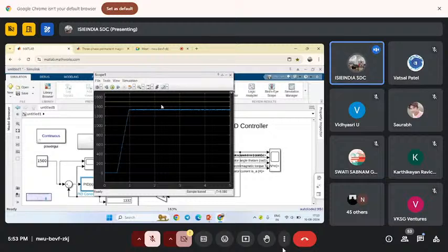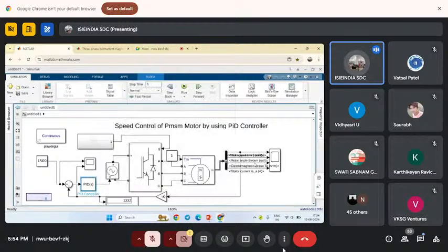It was stuck at 1332 because the KI value should also be taken into account. If you are increasing the KI and KP values approximately and correctly, then only will your controller reach the accurate speed. So the KI and KP values should be balanced.